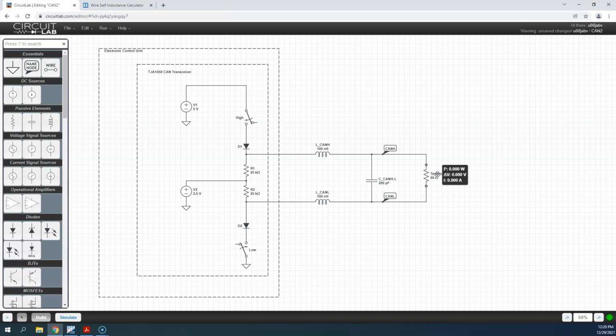So if you can imagine, this is a 5 meter long cable that has a terminating resistor at either end. We could kind of model it like this. It isn't exact, but it's a much better approximation than just wire, where we put no resistance. We said it has no resistance, no capacitance and no inductance, but in reality it really does. So we've taken that capacitance that I figured for 5 meters, it was 40 picofarad per meter. I've taken that, and so 5 meters of this gives me 200.